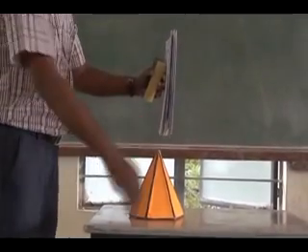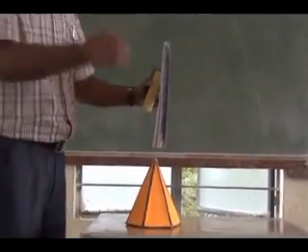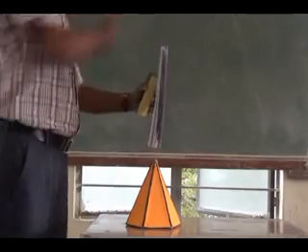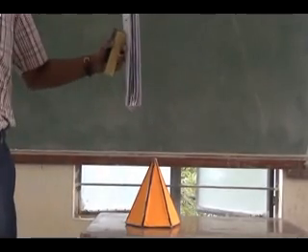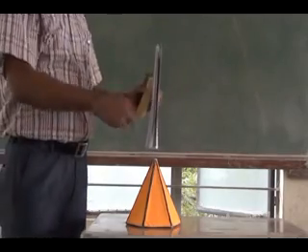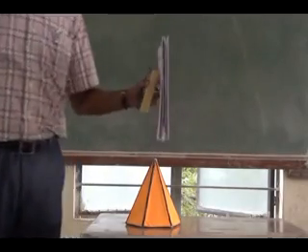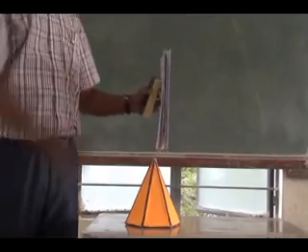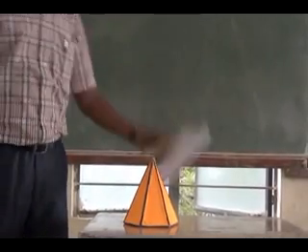It is perpendicular to HP. I have to represent it in the top view as well as it is perpendicular to VP. In both front view and top view I will be showing my cutting plane as a line. Then where will I have my true shape? Auxiliary plane, that is on the side view. Right. So this category, make a note.